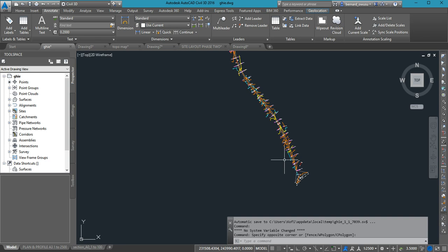So somebody should give us a typical road cross section in terms of the width. Carriageway width, what carriageway width are we using? Okay, so the carriageway will be 7.3. Then are we going to have shoulders or walkway? What's the width? Let's say a shoulder of 2.5. So we have 5 plus 7.3. Is that 12.3?